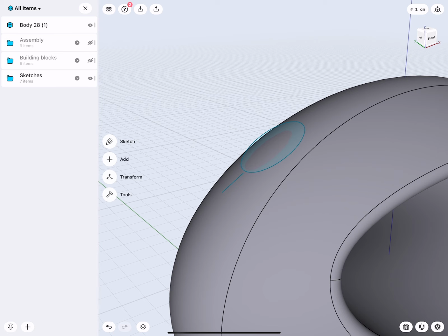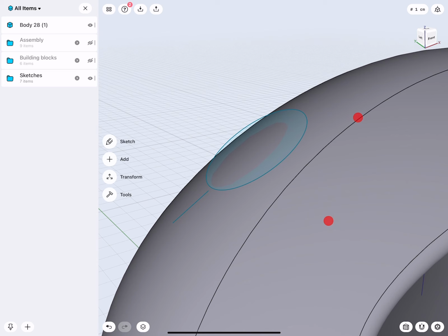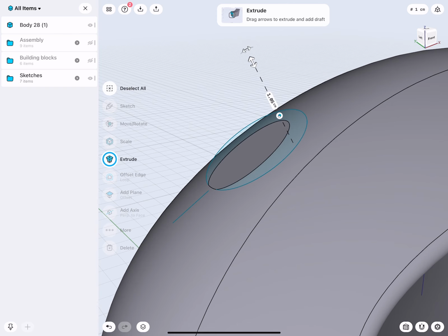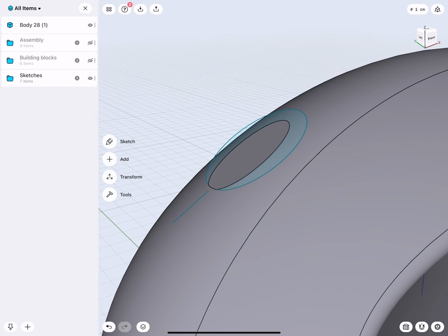So now the question is, do we want to make a button that will actually be fused to this model? Or let's say later we would like to 3D print this and have maybe a button we could take out. So it's a question, do we extrude and join, or do we extrude cut and then rebuild a button one more time? In this case here, I will use this in the sense of making a cavity into which we will model the button.